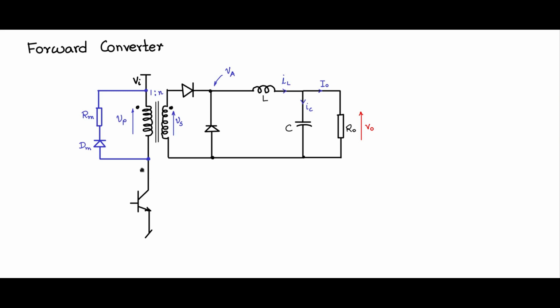So now when you switch this on, there is a current flow through the magnetizing inductance and the load reflected current flowing through this, and when you switch off, there is no load reflected component, only the magnetizing portion of the current will freewheel like this. It will decay with the Lm by Rm time constant.